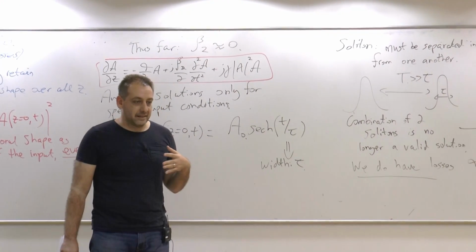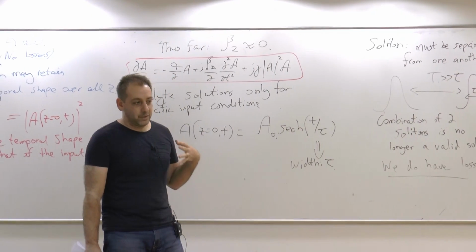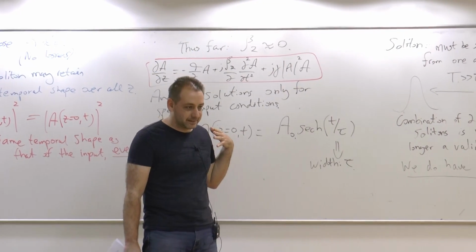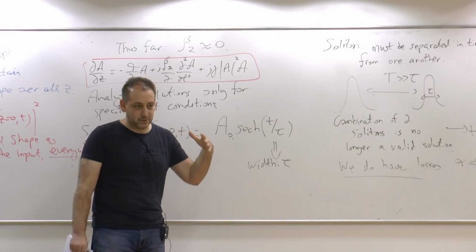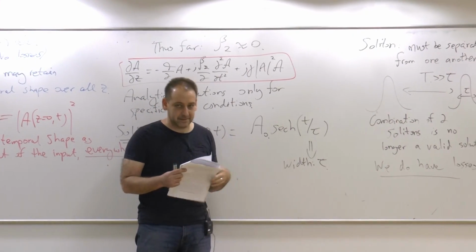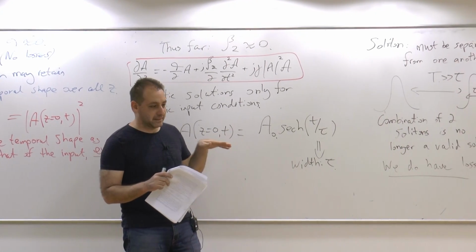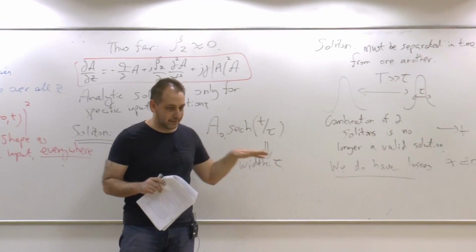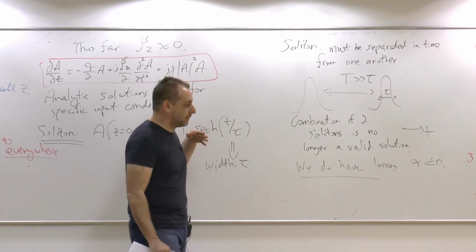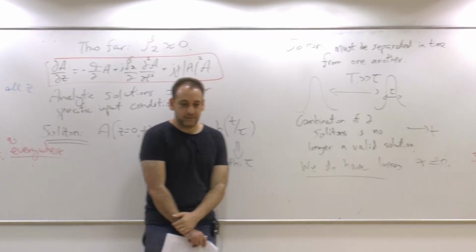And in reality, you can make a fiber practically transparent. If you balance your amplifiers just right, it is possible to take out losses with good precision, so power is not lost and not gained, and the medium becomes in effect transparent.